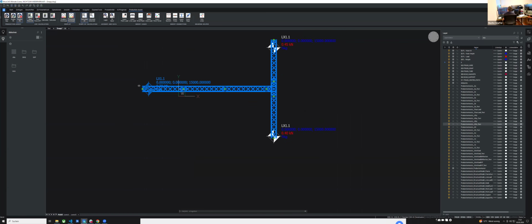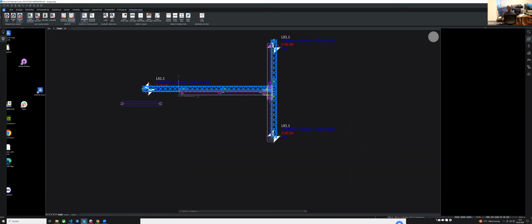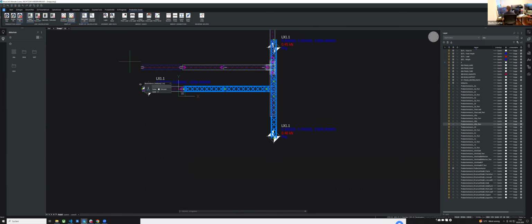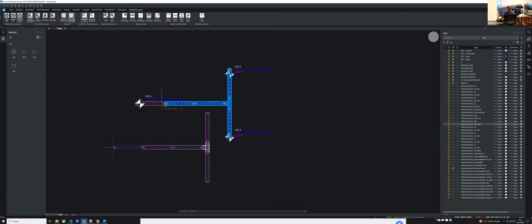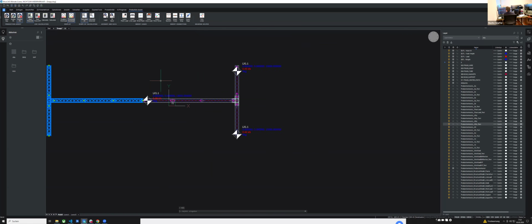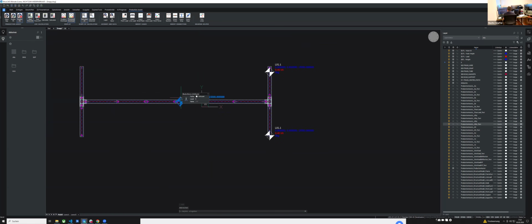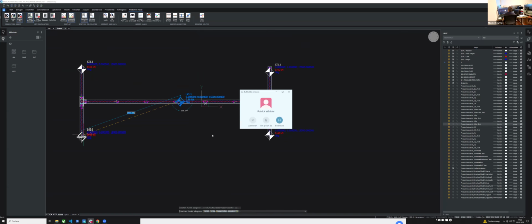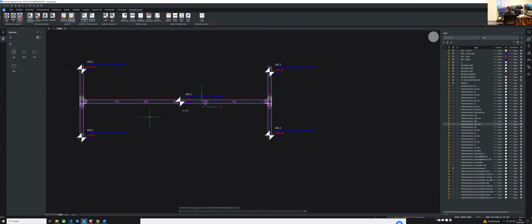This is also working when you have multiple things in here. So if you have all of them selected, you hold the Shift key pressed, and then you will see it will automatically be able to be copied in here. So copy it like this, and then snap it to this functionality. Sometimes it's a little bit challenging to snap it to the right thing. When I now start copying, I can copy the hoist in here like this, and then there's obviously someone calling. With this, I have the new hoist in here.